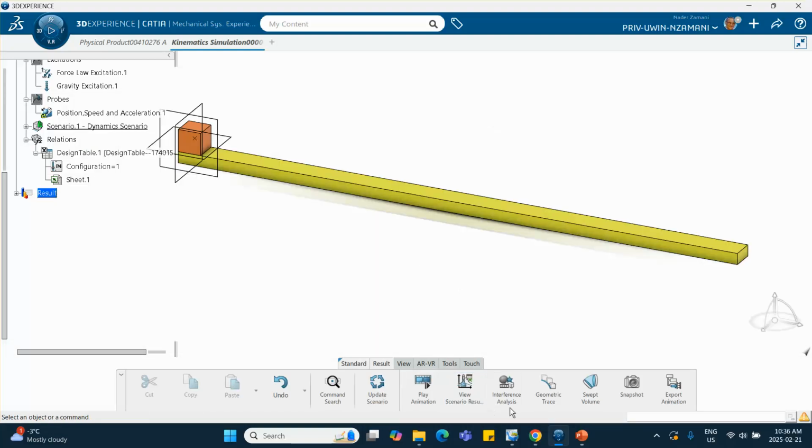So that takes care of this tutorial. The moral of the story is that if you have to do initial condition for velocity, to the best of my knowledge, there is no way of directly doing it using the icons and the functionalities that are available here. I gave 2 problems where I did that based on defining an impulsive force, and then that impulse turns into initial velocity, and these are tutorials 29 and 30, which is just it. All right, folks, good luck.